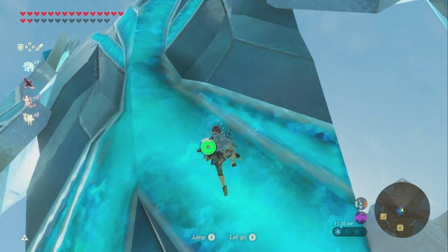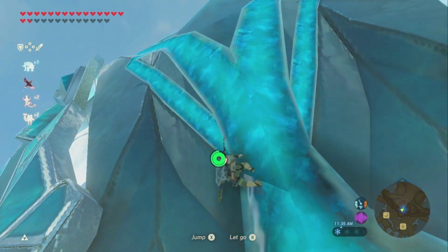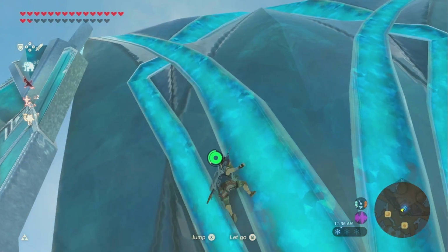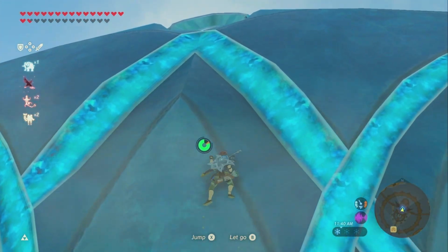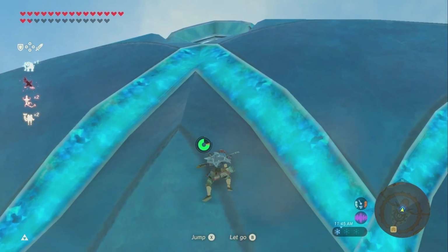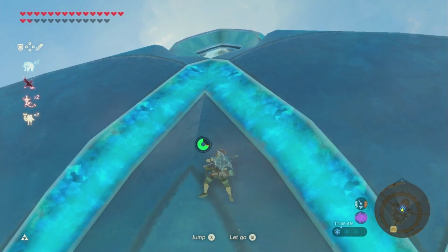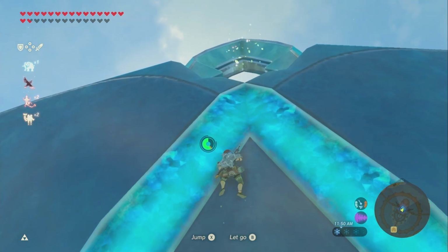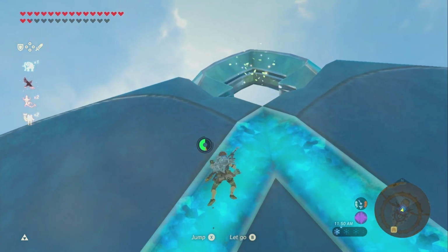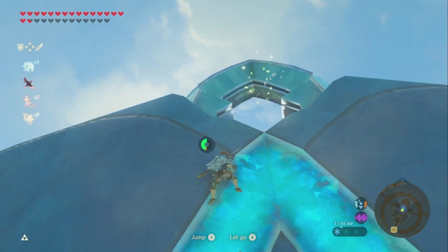The burners on these systems can be as large as 100,000 BTU per hour input, since many are designed to provide domestic hot water and space heating as well. We'll get to the space heating side in a minute, but let's have a look at what these water heaters do that is unconventional.